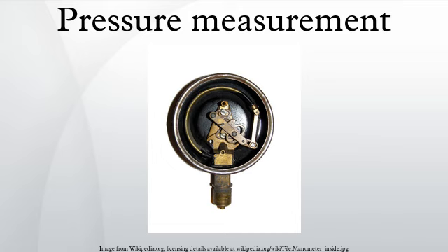McLeod gauge. A McLeod gauge isolates a sample of gas and compresses it in a modified mercury manometer until the pressure is a few mmHg. The gas must be well behaved during its compression. The technique is slow and unsuited to continual monitoring, but is capable of good accuracy. Useful range: above 10^-4 torr, as high as 10^-6 torr.